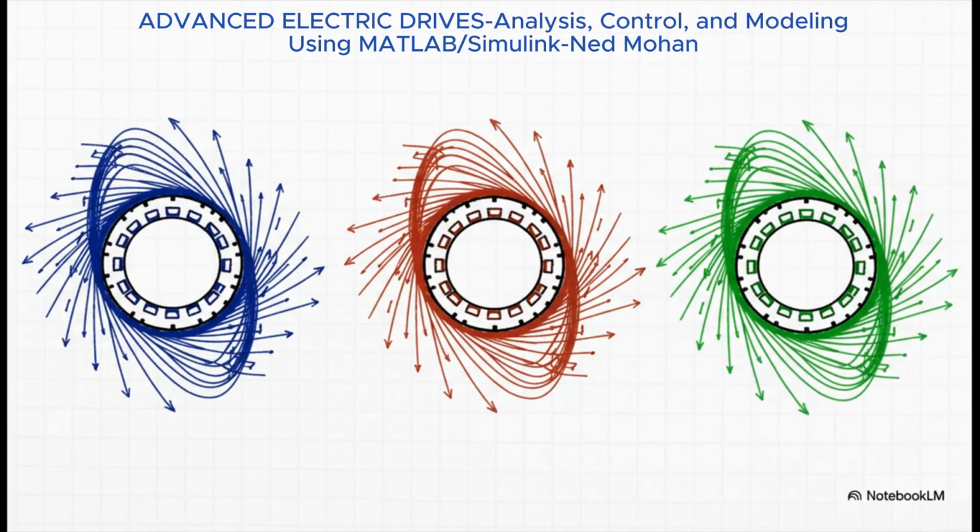The really key takeaway here is that the windings for B and C are basically clones of A. They work exactly the same way. When current flows through them, they each produce that same beautiful cosinusoidal magnetic field. The only difference is where their fields are pointing in space. They peak along their own magnetic axes at 120 and 240 degrees.